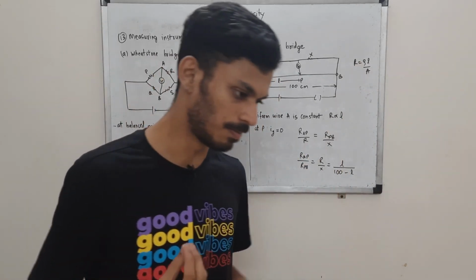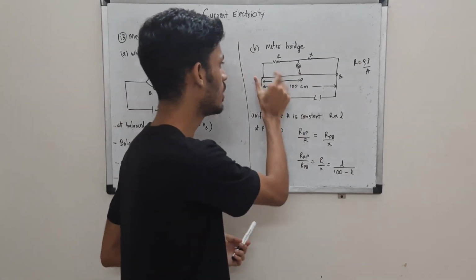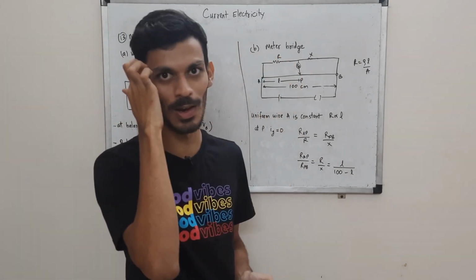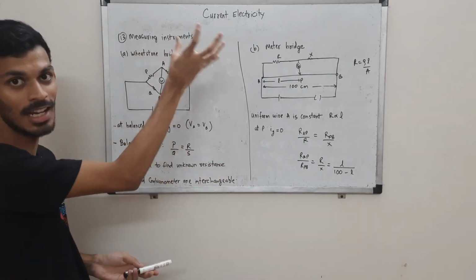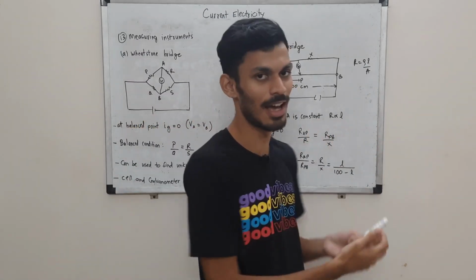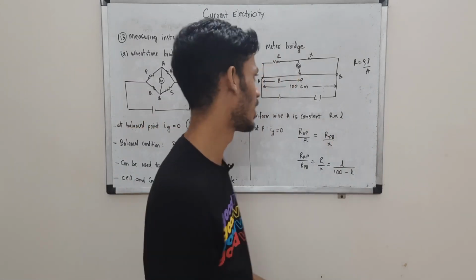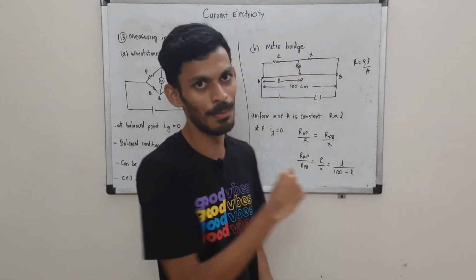The only changing factor for resistance is the length. As you change the length, the resistance of this branch will change. That is the idea here, where we were changing R. Instead of R, we can change the length, since length and resistance are directly related. So we are changing the length, meaning we are changing the resistance, until we reach a balance point.